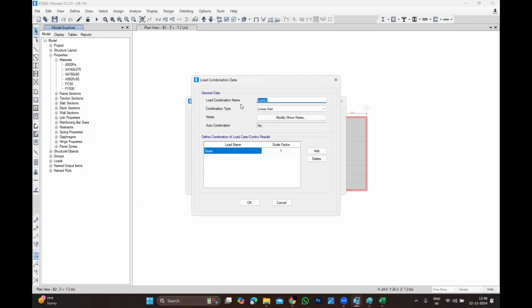You cannot be sure that this drift is not going to continue till the top. If it is slender, 100% sure it will continue. If it is square or rectangular, or even a bit of an irregular shape, no problem. But it goes like this. It's like what we used to call a bulb. The bulb will be created only in a certain portion, 3, 4 floors, 5 floors. There you can put an additional bracing or outrigger to control it.